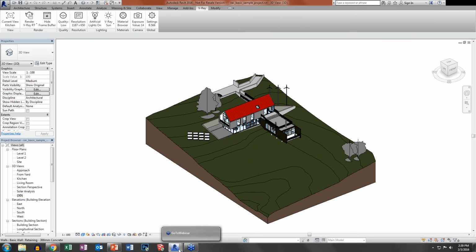So in the frame buffer itself, yes, but natively in the V-Ray for Revit toolbar, no. So you won't be able to put in your own number, for instance. But you can go into the V-Ray frame buffer and get much more granular control there of many, in fact, all of the same post-processing effects that you're familiar with from Max, Maya, Rhino, SketchUp also exist in the frame buffer for Revit, so you can do those overrides there.